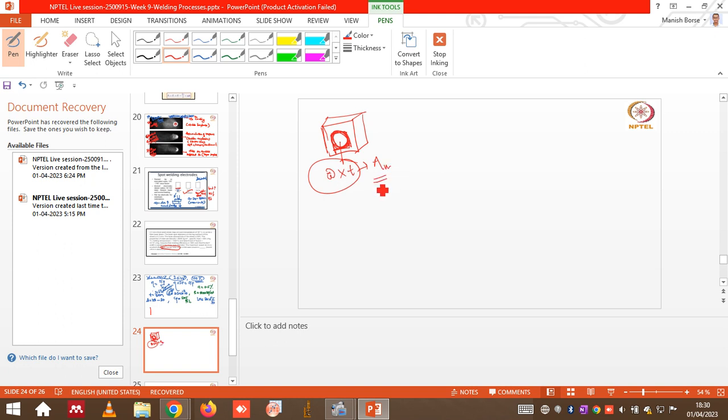And also we have the equation that input equals output, and they gave 2 kilowatt power, so obviously 10 raised to 3 we have to multiply with the absorber efficiency, right? So this much is the input power, but out of that only 50% is actually absorbed by the steel surface.